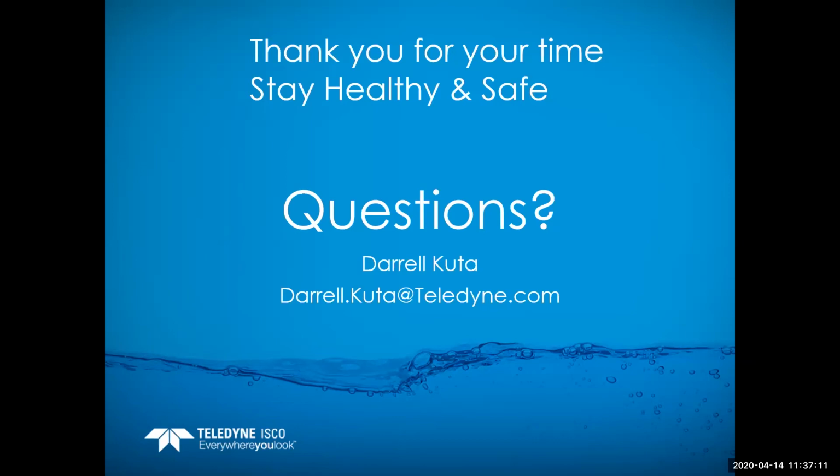So if your water depth was 6 inches and you rotate it up off the side, you're still going to calibrate the water depth to 6 inches, and then it's still going to be able to transmit that continuous wave Doppler signal. The trick to it, though, is that we want to make sure that you still have about an inch of water over the top of that sensor to get a velocity reading. I don't have exact numbers, but the accuracy isn't going to be affected very much by having it rotated off the bottom of the channel.